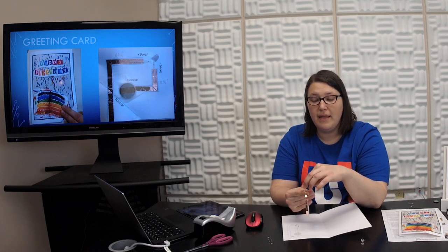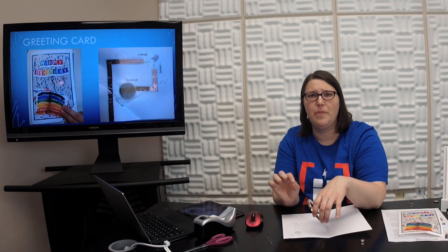Some of the copper tapes you buy are copper tape, but the adhesive itself isn't conductive. And so that also can create a problem. But just again, make sure that it says when you buy it, conductive adhesive copper tape.